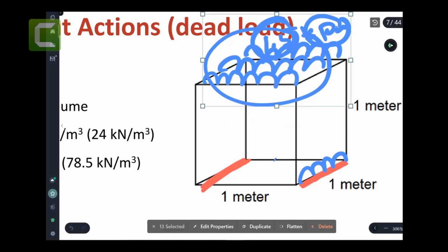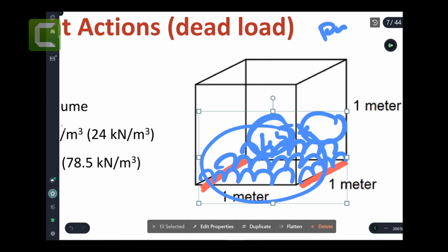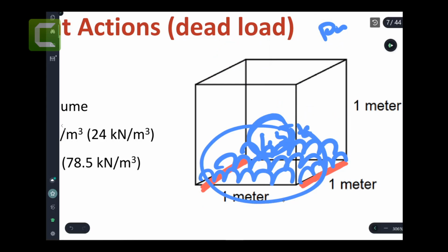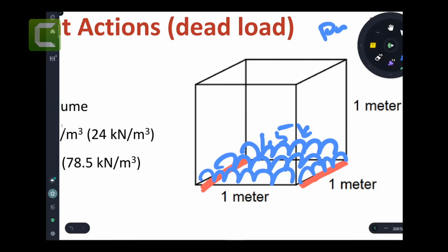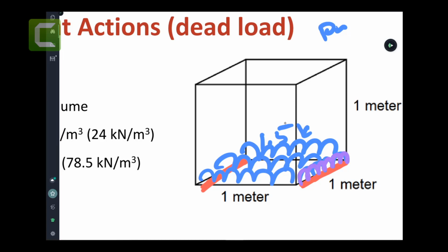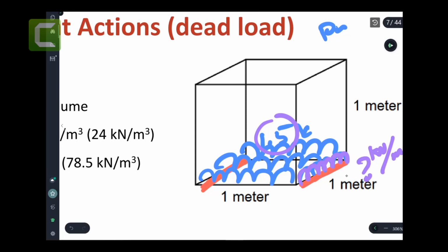it's actually still applied. I'll just move it down. It's still applied down the page. Just delete those additional circles. So imagine this is the pressure. It's like a blanket. You imagine you have laid a blanket on the floor, but it's heavier. It's 1.5. So it's a pressure. And what I'm asking you, can any one of you tell me what line load we eventually have from this pressure? Remember, line load units are kilonewton per meter. So how to calculate this?